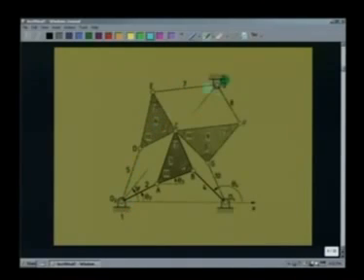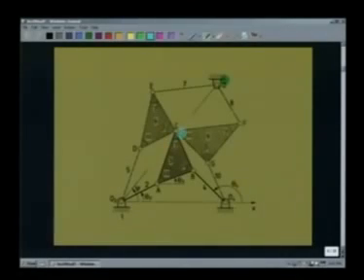Now, all these three 4-bar linkages have the same coupler point C, and this assembly moves in a unique fashion. In other words, there are 3 different 4-bar linkages which can generate the same coupler curve at the point C. As a result, this gives a wider choice to the designer to choose one of these 3 linkages to produce the same coupler curve.